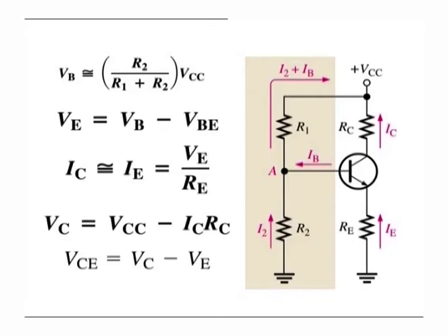All circuit design involves trade-offs, and one trade-off is that stiff voltage dividers require small resistors, which are not always desirable because of the potential loading effects on other circuits and added power requirements. If the circuit designer wanted to raise the input resistance, the divider string may not be stiff and more detailed analysis is required to calculate circuit parameters.